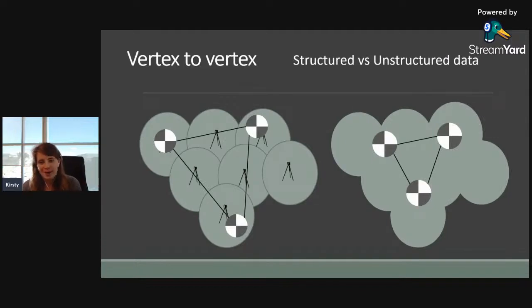So another key point I want to make here is that it's possible to apply your control to a locked or an unlocked point cloud. So what do I mean by that? Well, do you want to let your targets with your control fit to your point cloud and move your scans around? Or do you want to put them onto a fixed point cloud and get residuals for those errors without actually affecting the registration? So whether you decide to do it locked or unlocked, that affects the error propagation throughout the data set.